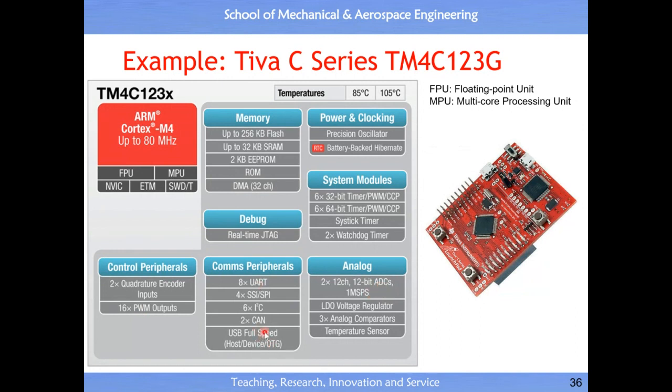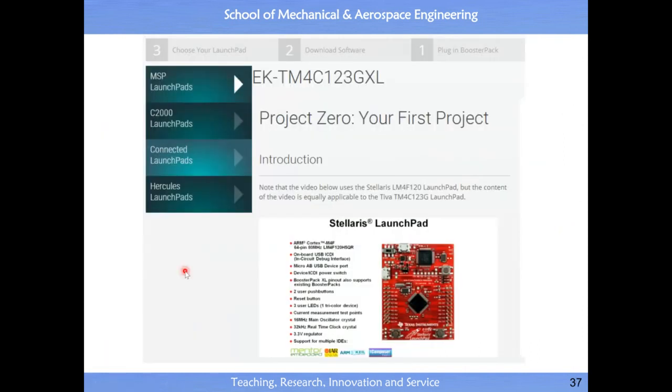And we also support data communication. There's an I2C bus, CAN bus, USB. This is very low level. With this tool, you can do anything you want. Invent your own protocol of data communication. So this is a serial communication. And this is the universal serial communication, receive and transmit. A means asynchronous. S here is synchronous. You can do both. Asynchronous is for long distance communication. This is good for short distance communication. So it's very, very powerful hardware.